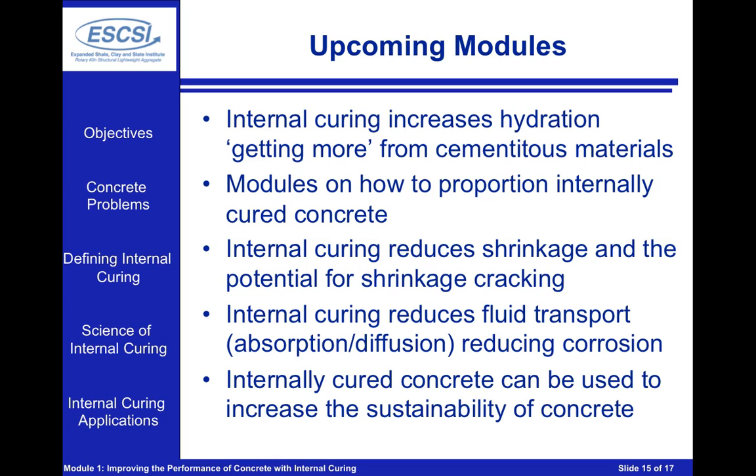Finally, what we're going to really focus in on is how internal curing can be used to reduce fluid transport, which will make it more difficult for the steel inside of our internally cured concretes to start to corrode, because it's going to take longer for the chlorides to get there. And by doing this, we'll be able to increase the sustainability of our concrete.